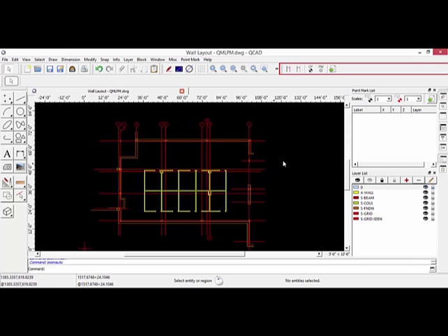Here, I want to start creating the information that I need for layout. This particular version of QCAD is the one that you download from Spectra Position, and they have highlighted the toolbar that we're going to be working with most. In here you see that we have our control lines. We're going to establish control lines, and we're going to establish a reference line. Then off of those, we're going to establish some control points. After that, we're going to create our point marks to lay out our walls. And lastly, we're going to export those points out into a CSV file so we can import it into our controller or our tablet.